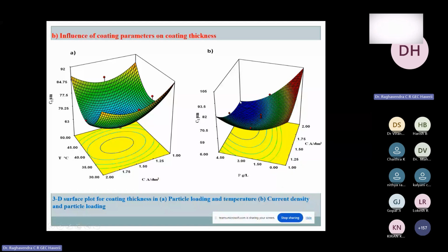What happens? The primary coating material is in micro size and the secondary coating material is in nanoparticle size. Because of this size difference, density differences and characteristic differences, there is always variation in the turbulent kinetic energy of the particles tending towards the target or substrate material when a composite blended powder is made with minimum coatings. This is how we analyze and optimize the coating parameters.